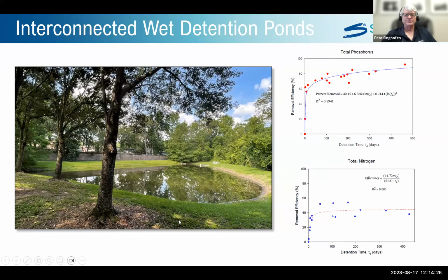But yeah, that structure, just the way they have this T coming out, it's just PVC and it's just kind of hanging there, not supported. So I wouldn't like to do things like that. I like to put a U-wall with a structure and then put a PVC T in with a clean-out cap on the top, and then make the T bigger than you need, but then cap the bottom and drill a hole in it. And that serves as a pretty good skimmer.